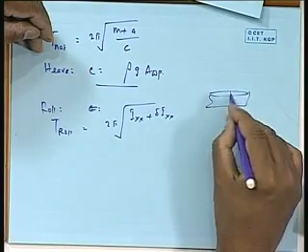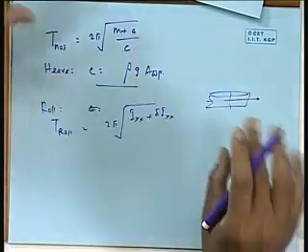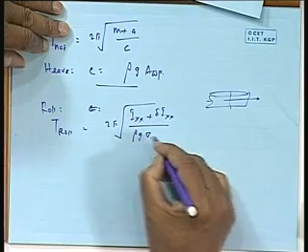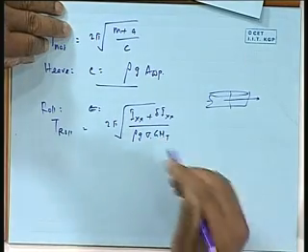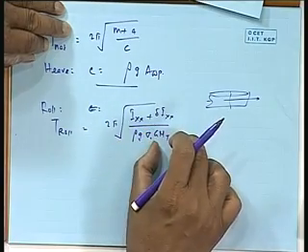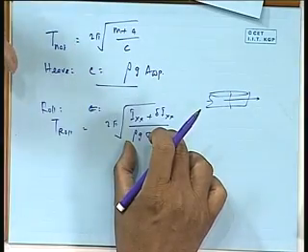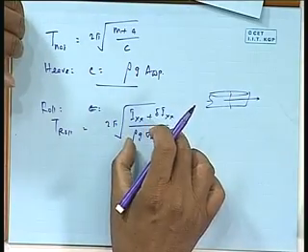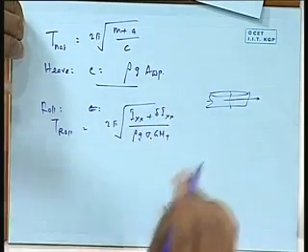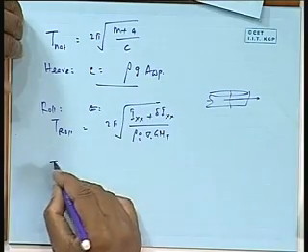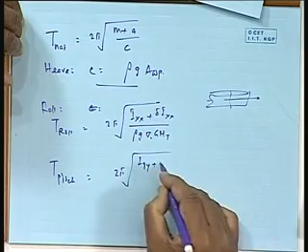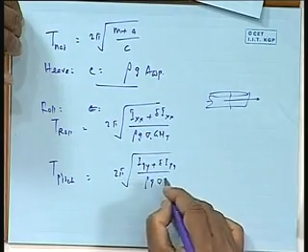Ixx is nothing but the mass moment of inertia about the x axis, divided by, now this C here becomes rho g V into GMT. It gives weight into GMT, because weight into ZZ is the restoring force, and ZZ is GMT into theta. Therefore, C becomes weight into GMT. That's what it becomes. Now, T of pitch will be 2 pi root of Iyy plus delta Iyy over rho g V into GML.